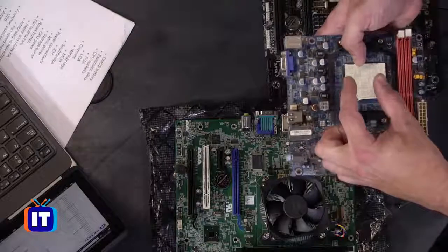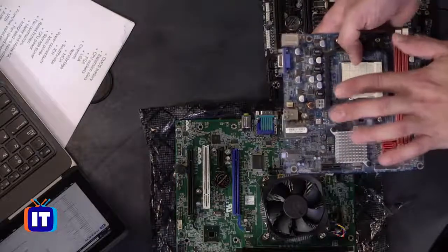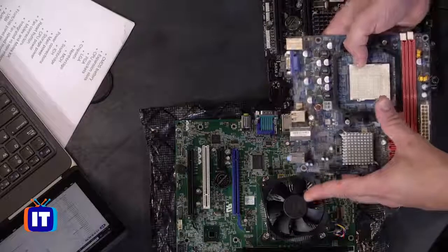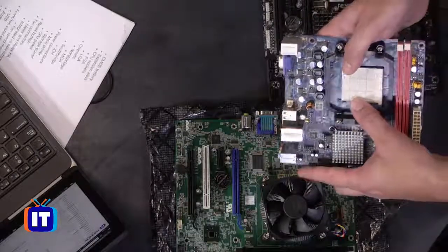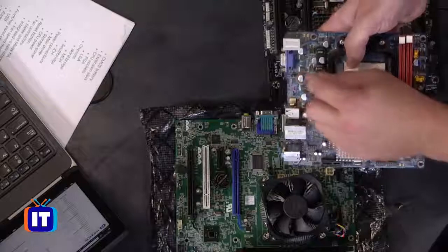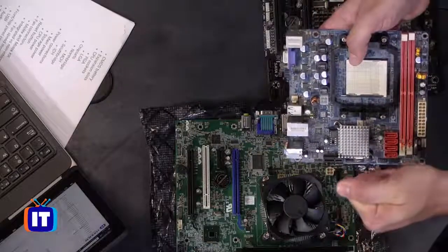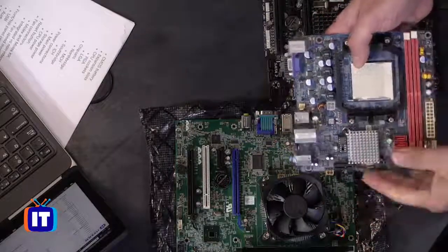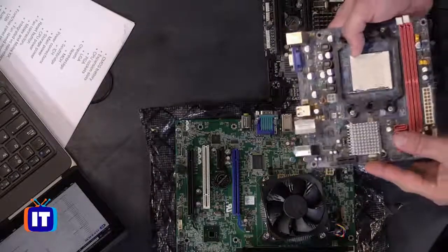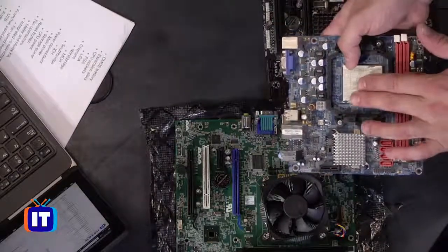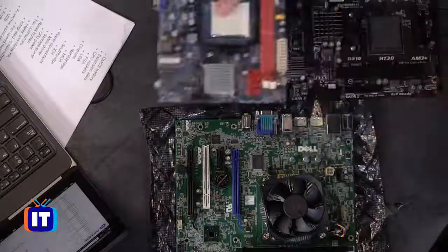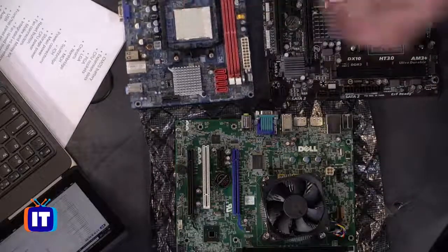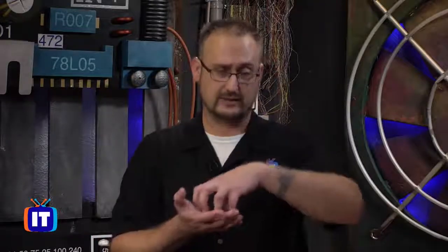And you could literally just drop that in there and shimmy it a little bit and you'll feel it drop into place. And then you take this latch and you push it down, right? And you'll notice it moves forward, and those pins get grabbed onto. This is what's known as a ZIF socket, and it's what we've used for a very long time now. It's called Zero Insertion Force Socket. So I want you to know the ZIF socket is the one that essentially will protect you from things like chip creep, the CPU walking out of its socket, and it also helps to prevent pin bending.